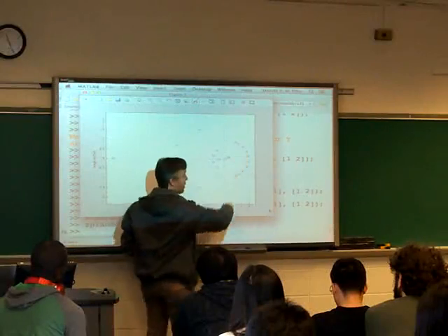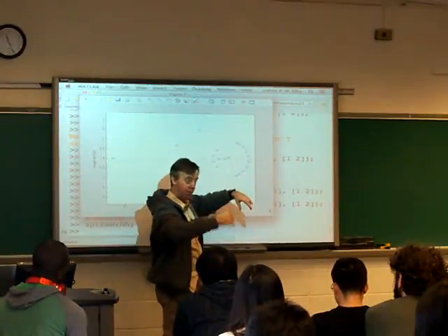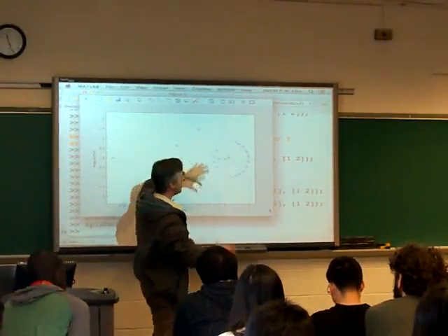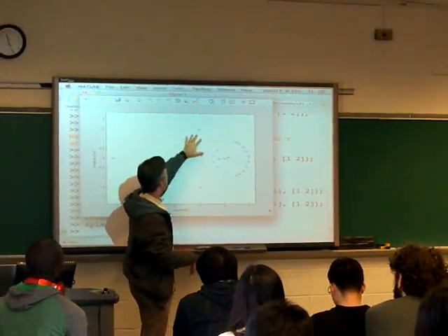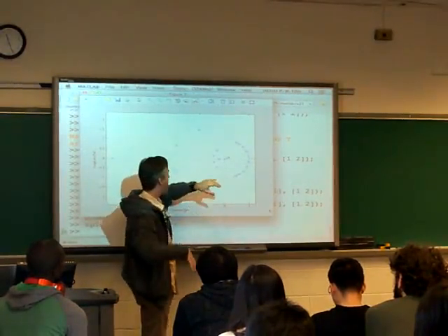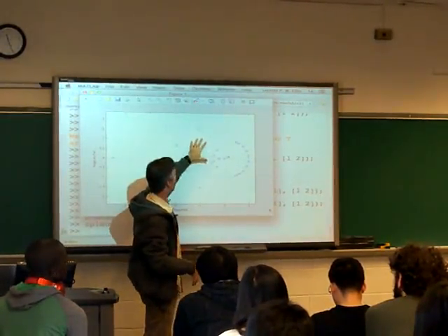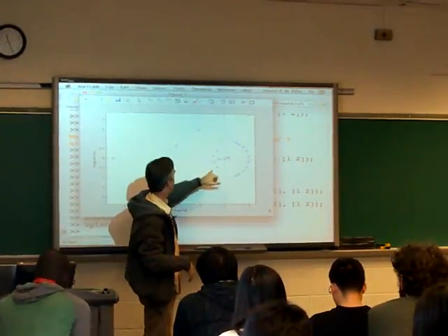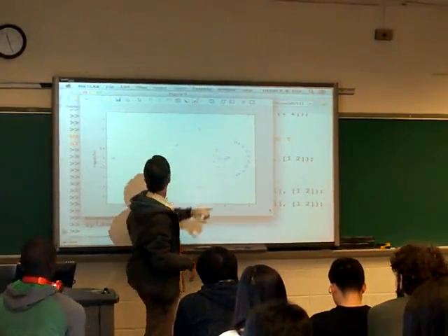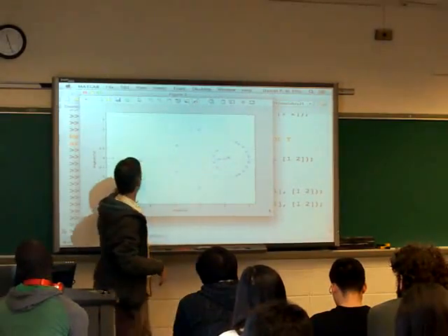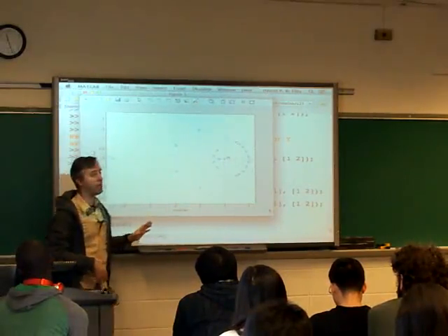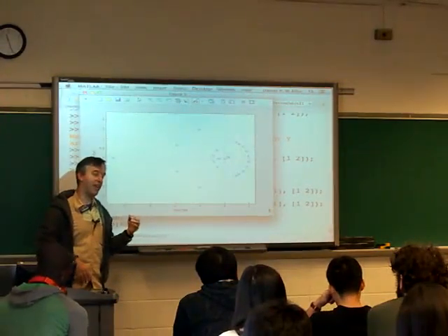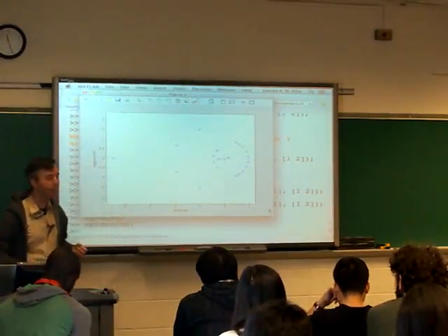So it has a bunch of zeros on the unit circle in the stop band, giving us the ripples, the deep notches in the dB frequency response. But in the pass band, to keep it equal ripple, we have a few zeros around here which are causing the minima in the ripples, but they're pretty far from the unit circle, so they're very, very shallow ripples. But they occur in reciprocal pairs and in conjugate pairs. They occur in groups of 4 here, and then there's a group of 2 here, just to stabilize that very extreme one. But this kind of structure is characteristic of a linear phase FIR filter. Okay, any questions about that?